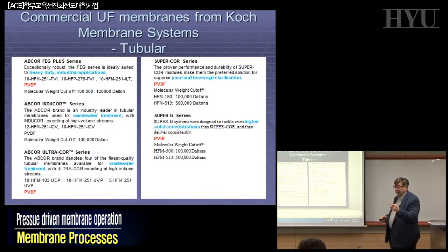To give you an example, a lot of biological substances, when in solution, can have different space configurations. Proteins, some polyelectrolytes, they just change. They can be linear, they can be globular. Now, by changing the pH, what is globular can become linear and vice versa. That means that talking about cutoff in this case makes no sense, because it's very much related to the configuration of the molecules in the solution. However, there was a big commission, and I worked for years trying to find a better definition of the selectivity of ultrafiltration.